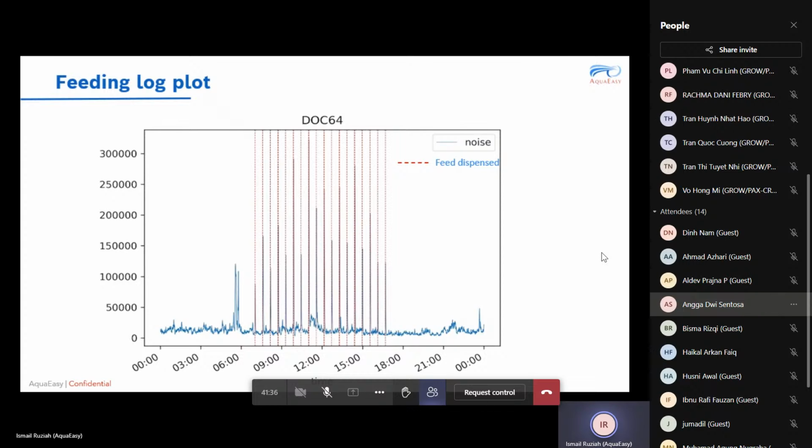If we zoom in, the hydrophone looks like this. I think most of you are also familiar with this. This large flat surface is the side that actually picks up sound, so this surface should face the auto feeding area. Also note that because the hydrophone cable is currently only 50 meters long, the location of the hydrophone must be within 50 meters of the control panel.